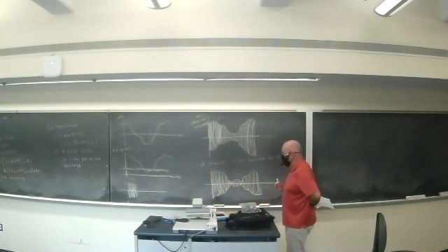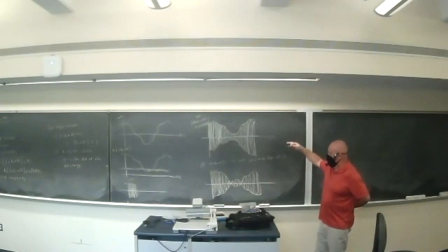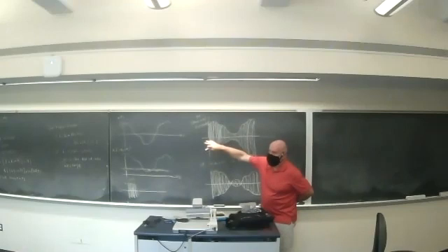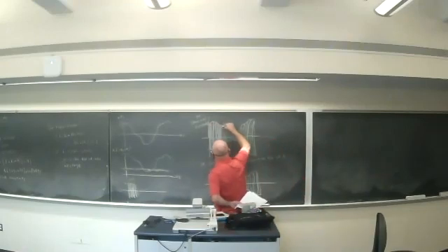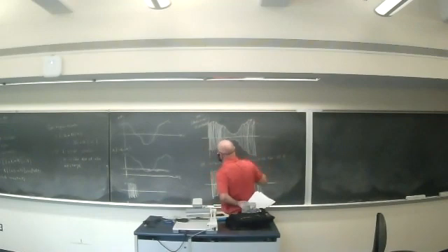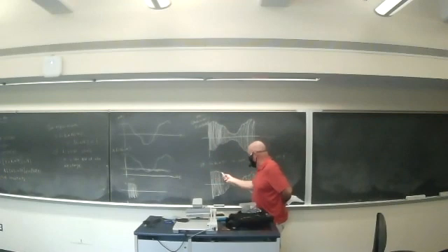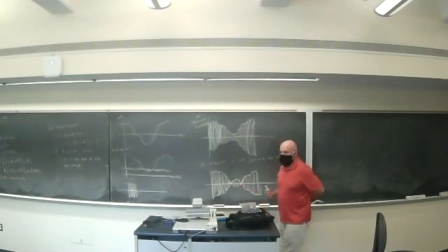Okay, my AM receiver does what's known as envelope detection, or, you know, we're going to look at a circuit that goes from this back to the message. Okay, but that circuit essentially just connects the dots here, connects the peaks of the AM waveform. Okay, the problem here is if I connect the peaks, that's the waveform I get, right? If I connect the positive peaks.